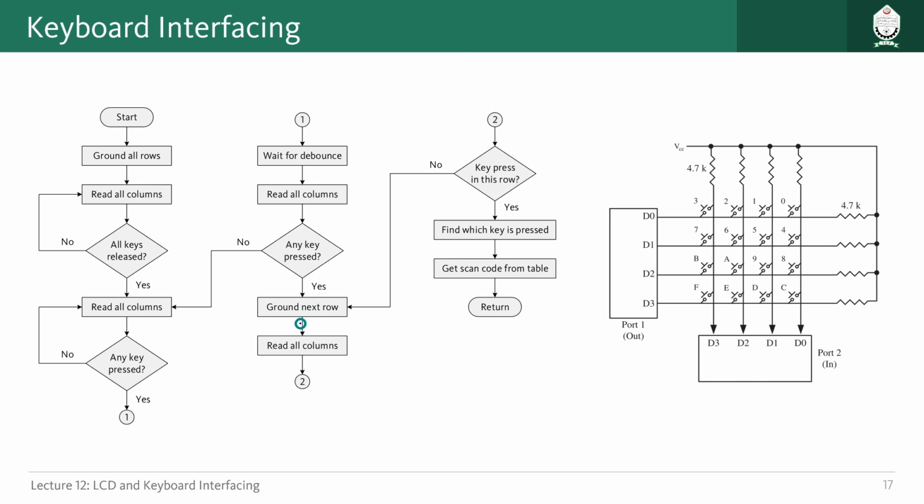As we said before, now we know a key has definitely been pressed, but we have to figure out in which column, as well as in which row, that particular key belongs. Then we can identify the particular key. So we are going to ground a specific row, first 0 1 1 1, then check all the columns to see whether they are all ones or not.